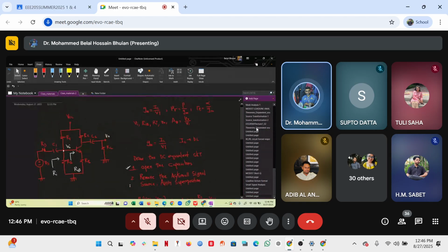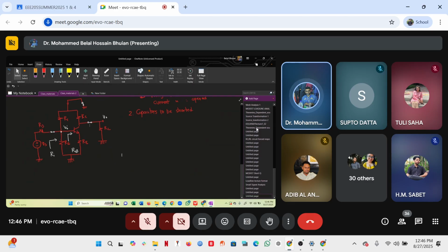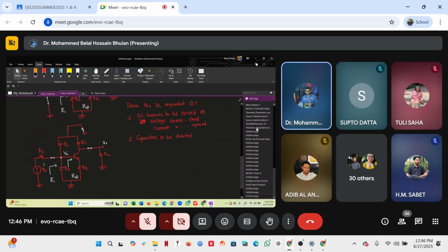When you have both DC signal and AC signal present, they see the same circuit a different way. To the DC signal, it's like a voltage divider biasing, as if RS and the AC signal source and RL are not part of the circuit. They don't see it. For AC signal, it doesn't see any DC voltage source. All it sees, the capacitors are shorted.